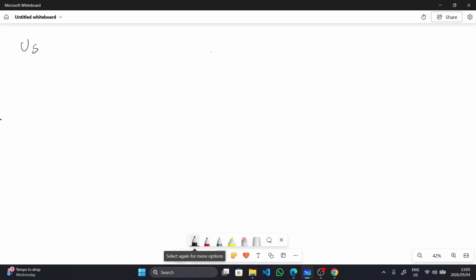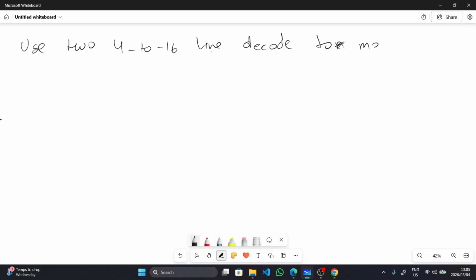Let's just use two 4 to 16 decoders to make a 5 to 32.